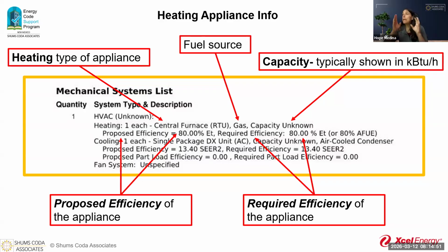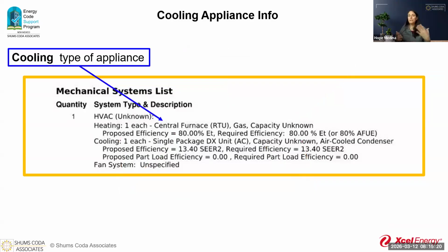So this actually helps you in not necessarily having to go through the 16 tables to try to figure out which one is the correct table and does this piece of equipment fall under this category or this category. It kind of does the work for you. I like to use the mantra work smarter, not harder. And mechanical COMcheck, you'll see here, after this class you'll be like, yeah, I love this thing too.